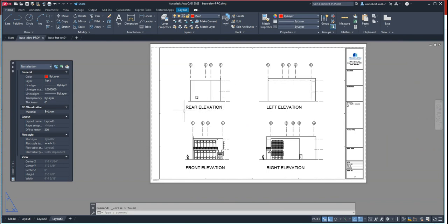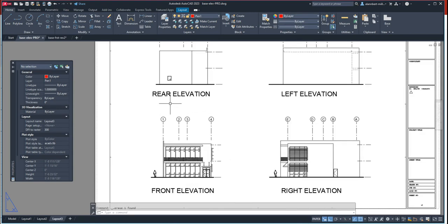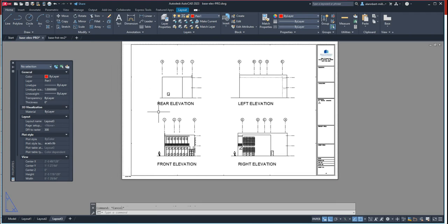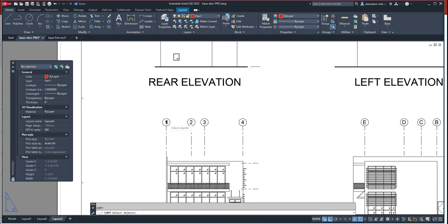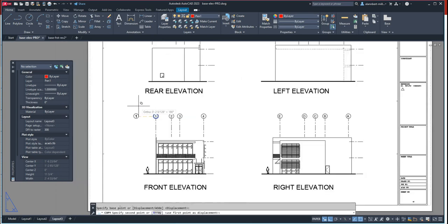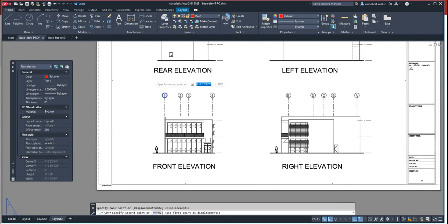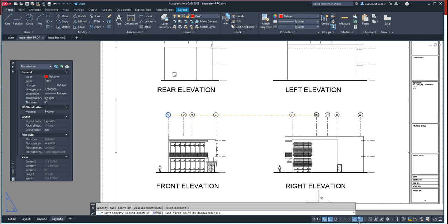They also wanted to put in a drawing number. Drawing number means that we're again going to put in a circle. Let's just copy this one. What they typically do is put in a circle wherever they want to, somewhere here, and then put a line through it, using line and its quadrant. Then extend that line up to the edge of the drawing, like so.